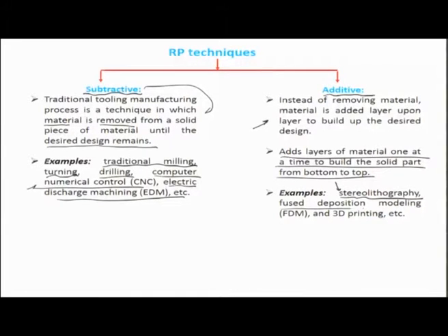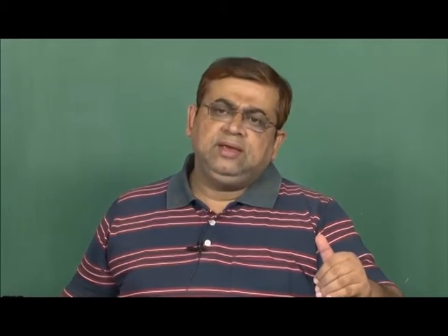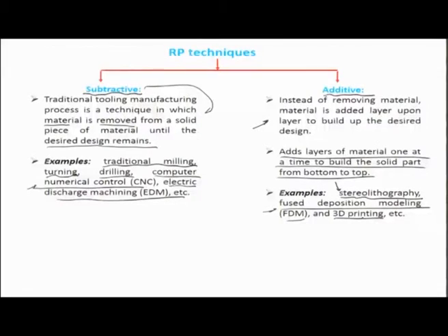Then you have fused deposition modeling, FDM, which uses single or two phase polymer systems, and the polymers are otherwise fed in as wires, obtained from billets, and then they are extruded so that there can be the deposition of the extruded polymer onto a bed using a track which is very well defined through a computer design process. So 3D printing in metals is another area where you're talking about additive manufacturing for rapid prototyping or